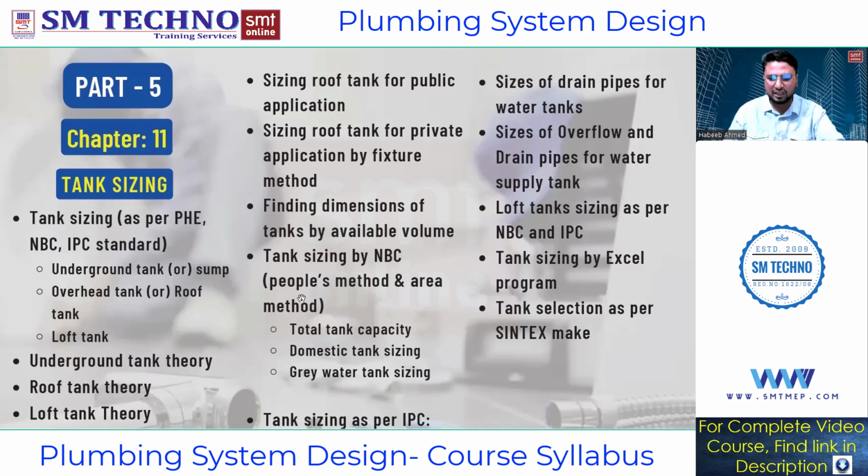Now tank sizing as per NBC standards, that is National Building Code of India. In this, I'll be dealing with people method and area method both. When we are dealing with NBC, one can find out the total capacity of the tank, domestic tank sizing, and grey water tank sizing. So what do you mean by these three terminologies? What do you mean by total? What do you mean by domestic? What do you mean by grey? We'll be seeing when we size the tank as per NBC.